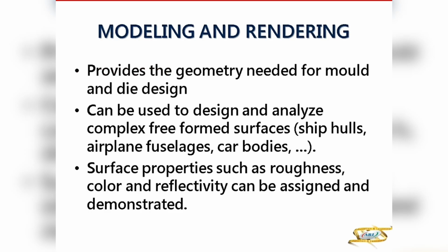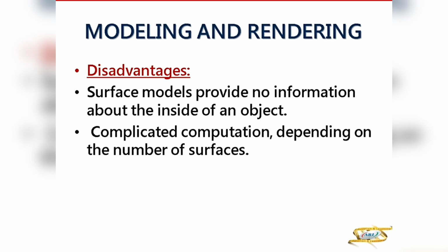the surface modeling. It will also analyze your ship's hull, airplane fuselages or the car body with the surfaces. Plus, you can also show the roughness, color and reflectivity of the surface. But the disadvantage is you don't get the depth of the model. So you can't know what is inside the model. You can just get the surface. It's a complicated computation depending on the number of surfaces, and it basically takes more memory than the wireframe model,